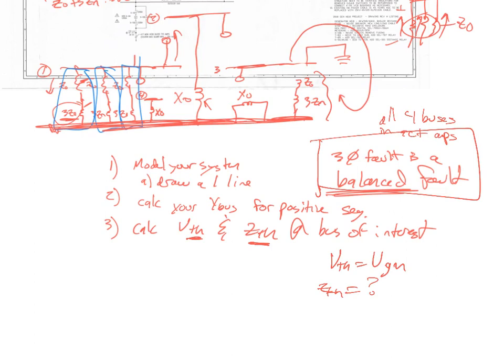Right there, and then you have to calculate V Thevenin, which is going to be the V of the generator. Let's just say it's 1 at an angle of 0. So there's your V Thevenin. I'll give you a huge hint. Now what? I've already told you what to do next. Solve for Z Thevenin. Once you have the Thevenin equivalent impedance, so this is bus 1, right?